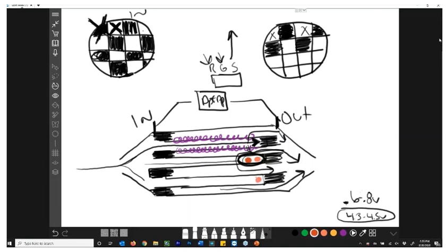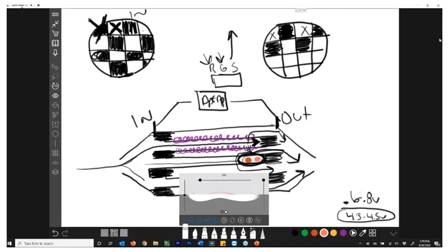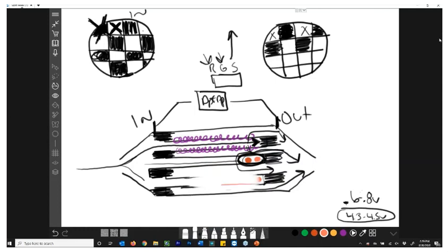So then we drive down the road some more, and we start building some soot, and more ash. All this constantly happens. Our chambers get full again. We run a regeneration. We have to oxidize that soot. So we run a regen, and we open up that chamber again. And once we open up that chamber again, guess what we're left with now? A little more ash. And this constantly happens till we get a little more ash and a little more ash and a little more ash.